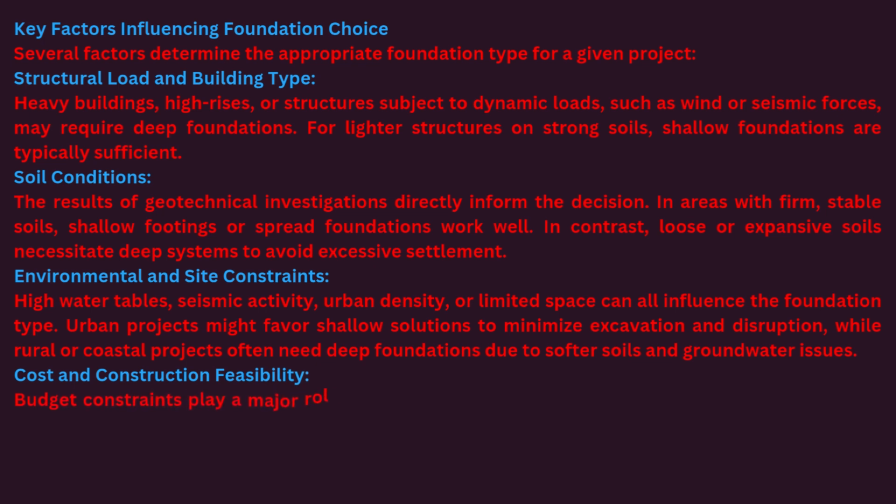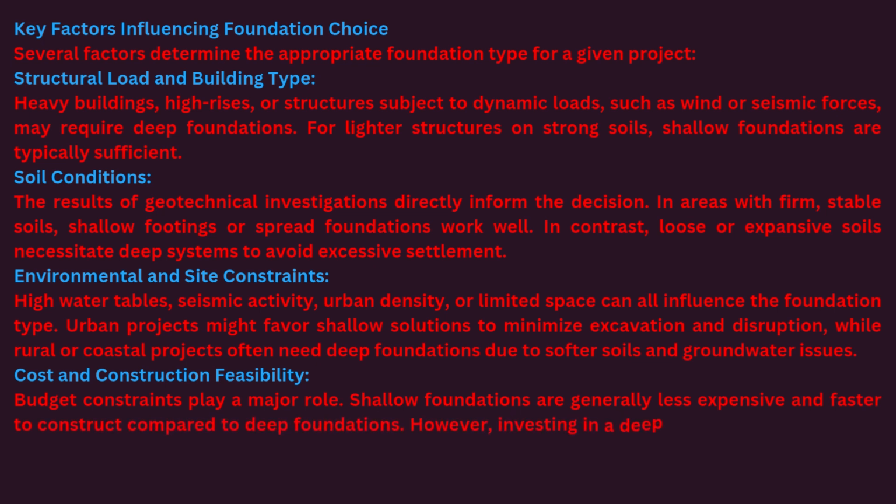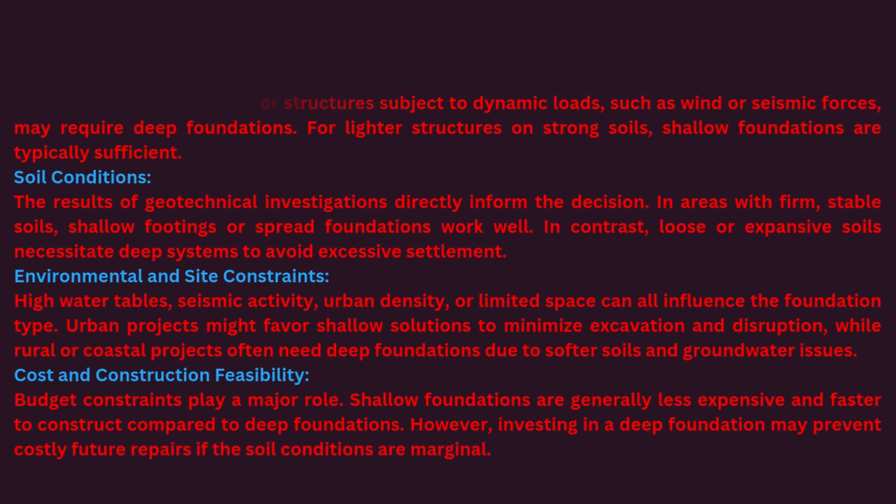Cost and construction feasibility. Budget constraints play a major role. Shallow foundations are generally less expensive and faster to construct compared to deep foundations. However, investing in a deep foundation may prevent costly future repairs if the soil conditions are marginal.